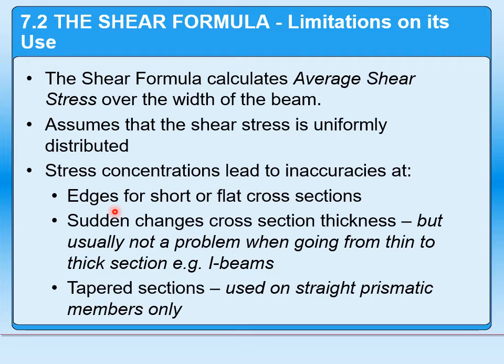This can be particularly problematic, though, if we have very short or flat cross sections. Turns out short or flat cross sections are going to exaggerate this effect, and we can get significantly higher levels of stress at the edges in those situations. So these need to be handled a little bit differently. So keep in mind, you cannot use this stress formula, this shear formula, for short and flat specimens.